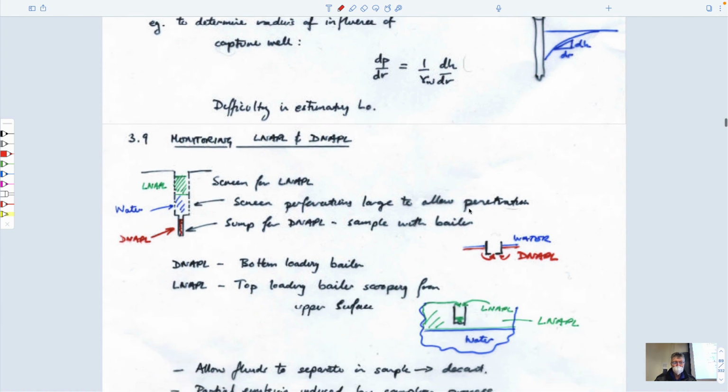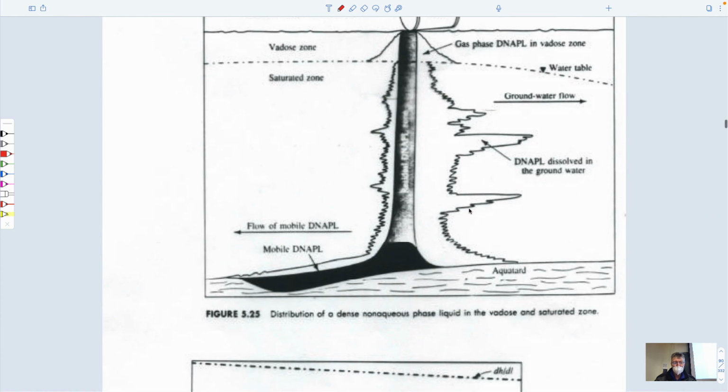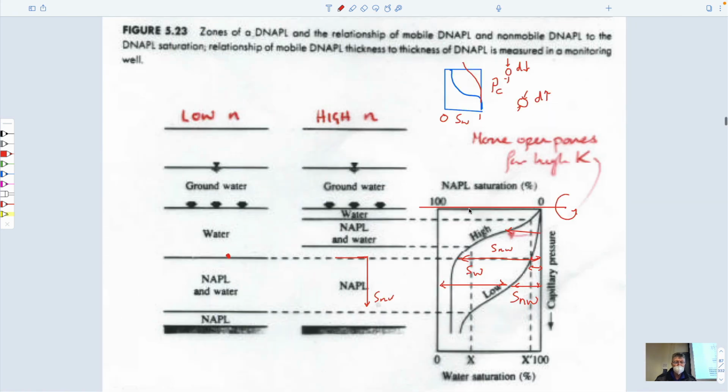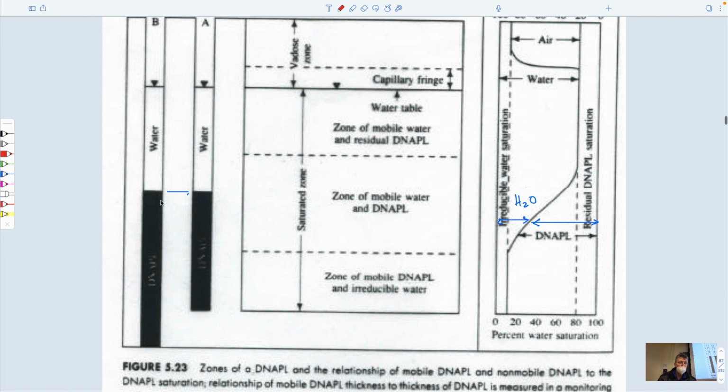And I guess the only final passing note is to make the case that was probably already apparent in this figure. If you have a borehole that goes to the center of the earth, then it's going to tell you that your thickness is infinite, right? Because this upper surface is defined by the capillary pressure versus saturation curve and is always the same. And so if you keep on drilling deeper and deeper, it would erroneously tell you that NAPL has gone much deeper, where it might be actually staunched by a capillary barrier, which you don't know would exist at some